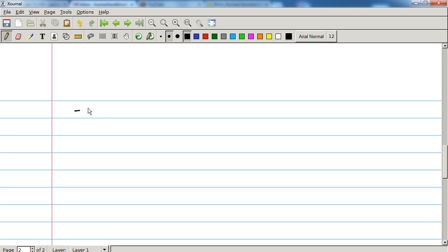So we'll use the number negative 4 again. We'll take the absolute value of negative 4, which is 4, which is the number you start with. You want to negativize 4. So you start with the number 4, which is 0, 1, 0, 0. If you want to use 2's complement, you have to use one more bit than the minimum you need to represent this number. So 4 can be represented in 3 bits. To make it negative 4, you're going to have to represent it in 4 bits.